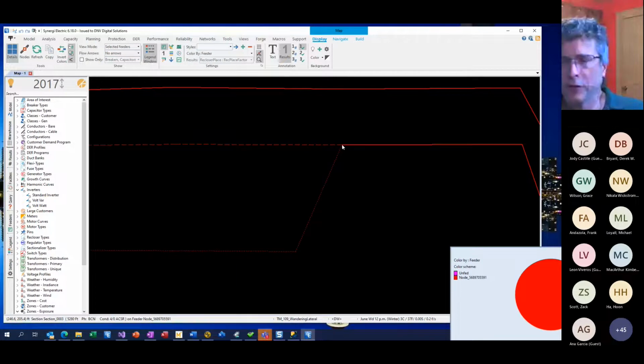So we do a sensitivity analysis. In this case we would run 3 load flows so that we get the columns of the impedance matrix. Then we take that impedance matrix, convert it to the sequence domain, and then we have Z0 and Z1. That's still going to happen if there are loops in the system.